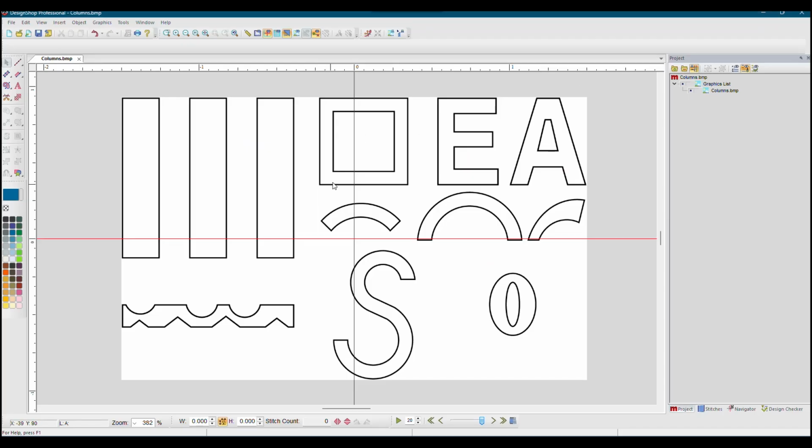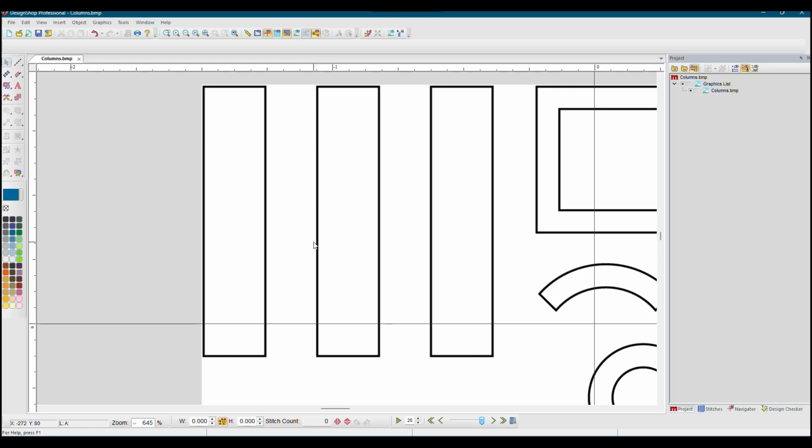So as I was showing the difference of the tools here, obviously column one, column two, single line input, and the last one here is pretty much complex satin. As you watch the other videos on how those tools work, this is just another way. I love the complex fill tool because it's controllable. You can adjust it on the fly, and where before it used to be just for fills only, now you can actually change it to a satin.